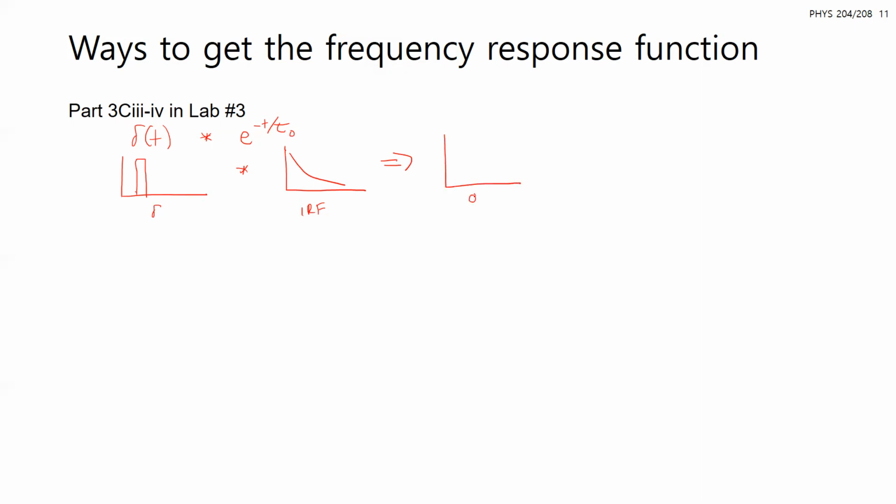in time would be the convolution, just like that cartoon I showed, where you would see the decay over here. This is where it's just starting to overlap. And then once it completely overlaps, you see the decay, and you can then fit this to get your time constant. And then if you take the Fourier transform, you're able to get that half a Lorentzian shape for your output in frequency to then quantify your frequency response function.